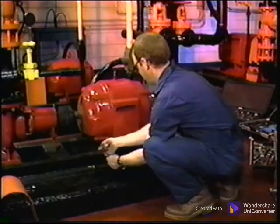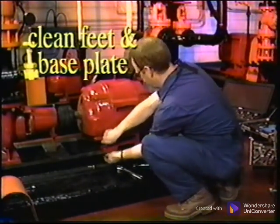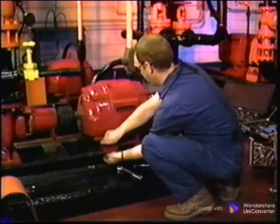Loosen the foot bolts and clean the top and bottom of the machine feet and the base plate, checking for any burrs or rough surface. A heavy-duty cleaning agent will help loosen and remove any residue. Check the foundation for cracking and loose grout. If the base plate has several coats of paint or is rough, it should be machined to a smooth surface.